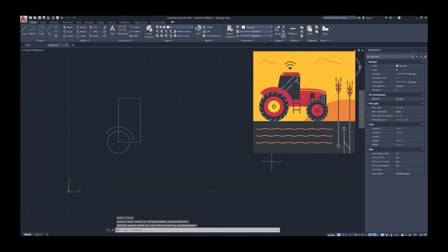So now that I've done that, next what I'm going to do is create an arc, okay? Just to give the cabin the look of our icon at the Bendigo Tech School, I'm going to arc this side, okay? So I'm going to choose the arc function, all right? I'm going to specify the start point of the arc. So I'm going to start the arc down.